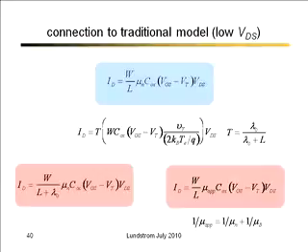Now, you can do the algebra a little bit different way if you like. Just collect terms a little bit differently. And you can write the current as W over L, not W over L plus lambda, but just W over L. And I can replace the real mobility by an effective mobility. What's the effective mobility? Well, it's the lower of the actual mobility and the ballistic mobility. So we've got two different ways that we can think about this.